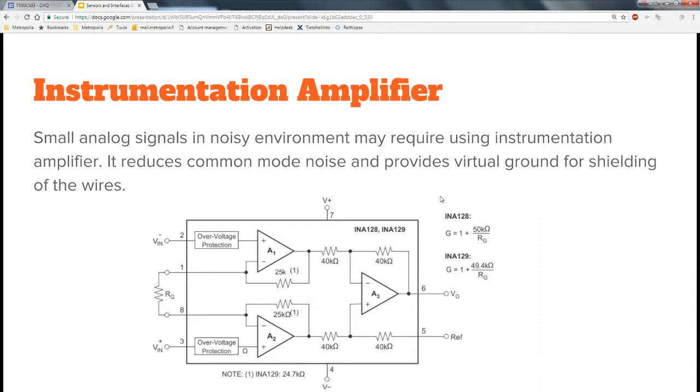Okay, huge electric drives, say a 100 kilowatt electric drive can be there, and then you are measuring something with very high accuracy and very small signals. You have big electric fields and probably also long lines from sensor to this box. You need to do something for the signal. You have to first have very good insulation, but not just that.